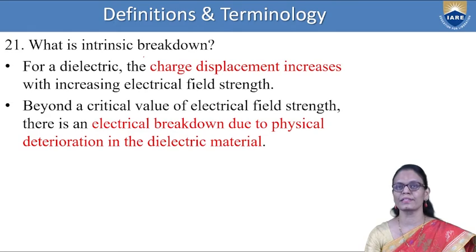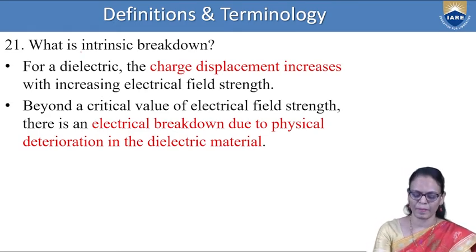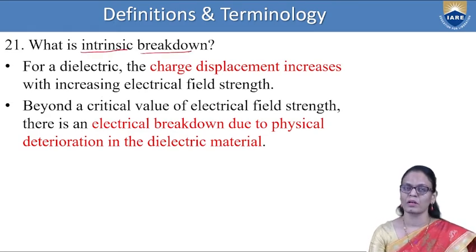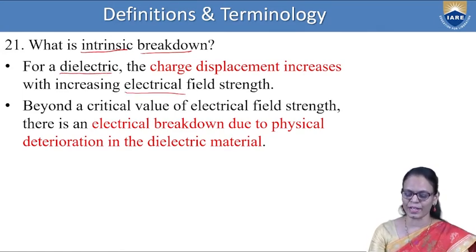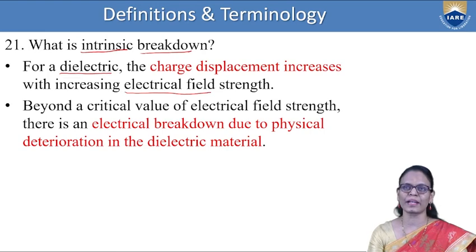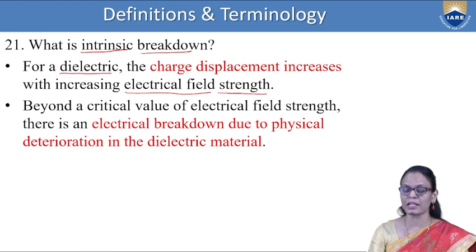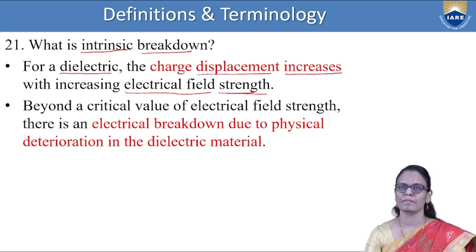So, what is intrinsic breakdown? Now, for a dielectric, the charge displacement increases with increasing electric field strength. This part we have already discussed. When we take a dielectric material and subject it to an electric field, the charges will get displaced. And as the electric field strength increases, the displacement also increases.